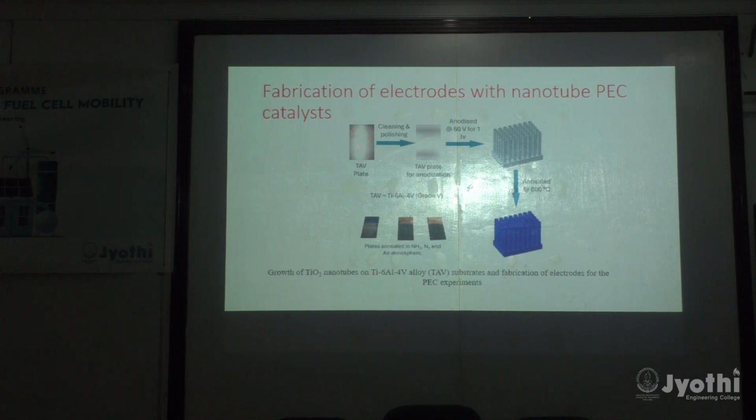Sometimes you don't have to have a purely titanium substrate. You can also use, this is actually a titanium, aluminum, vanadium alloy, TAV. So this is the substrate, a titanium, aluminum, vanadium alloy. You clean it, polish it, etc., then anodize it.